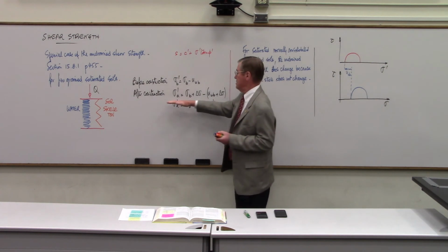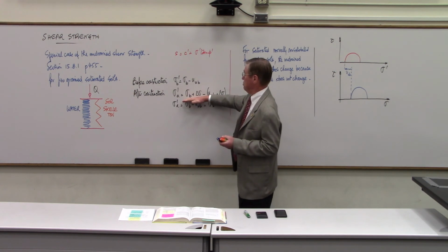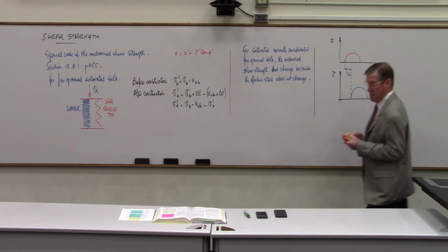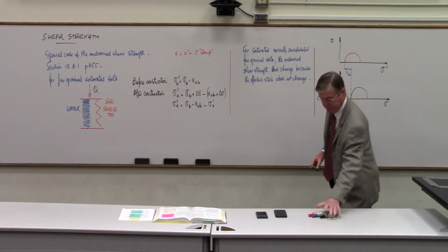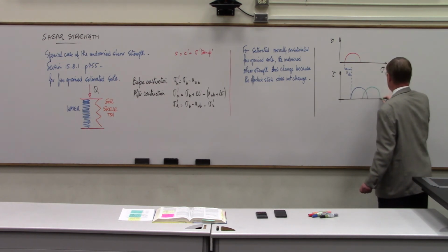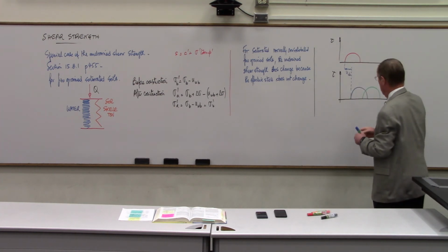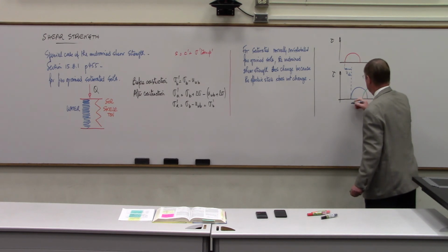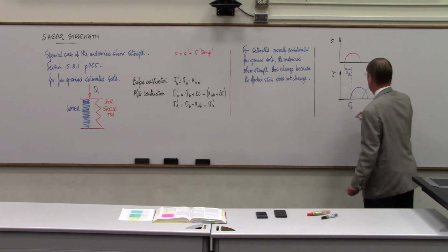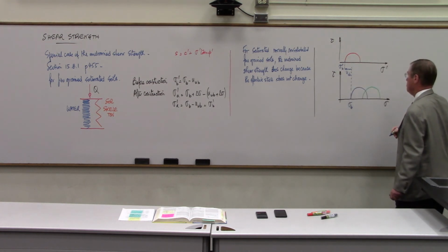If I now do another test at a higher total stress, sigma B after construction if you wish, I've increased the total stress to sigma B plus delta sigma. So now I've got a green circle right here. And I find out that the circle has the same diameter. Now the blue one was at sigma, what did I say? Sigma B. And so this would be sigma prime B, because I'm subtracting u_w.